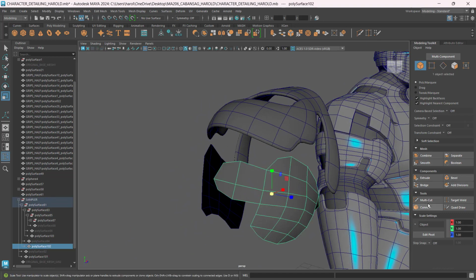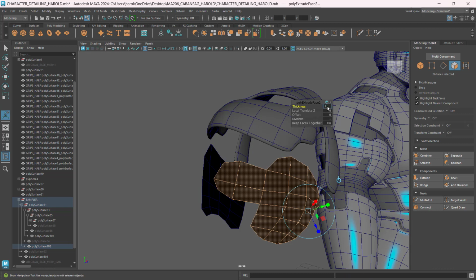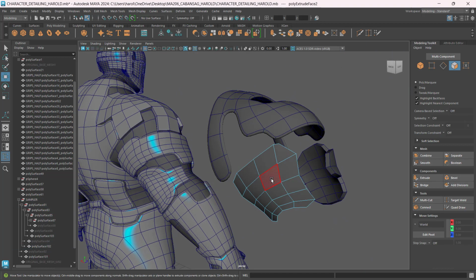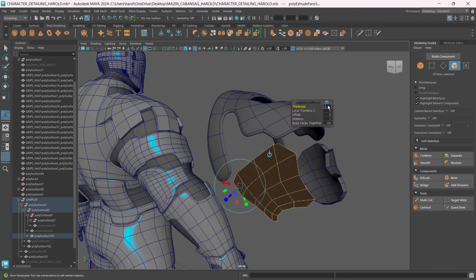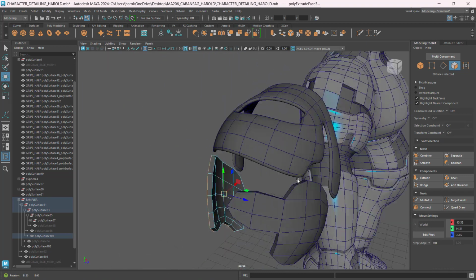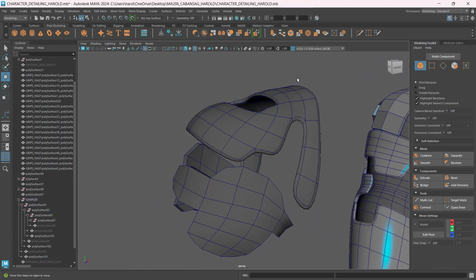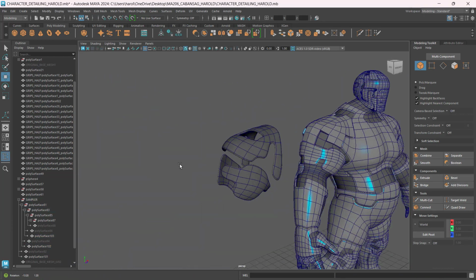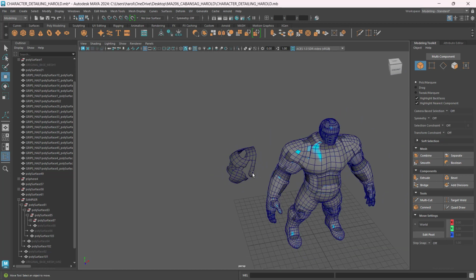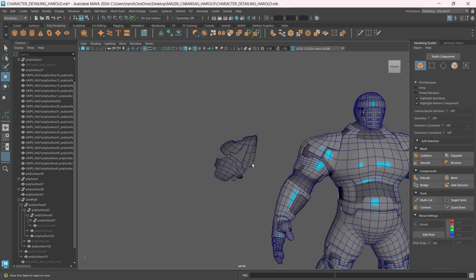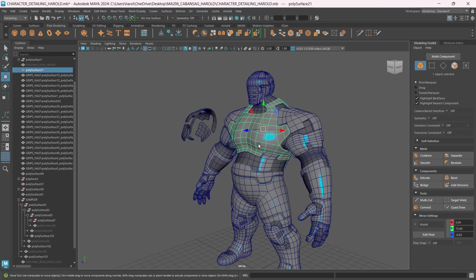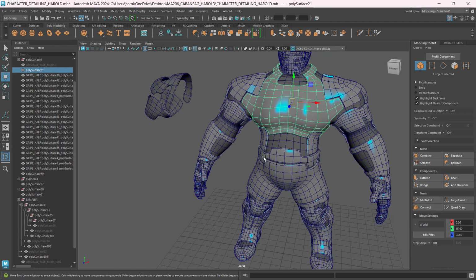So now I can just repeat, extrude, 0.15, enter, W, or switch to the move tool. Do the same here, double click to select all, and then extrude, same value, switch to the move tool. And then if I go for number 3 on both, so now I have this design for my character there. So that's how I have started the base.